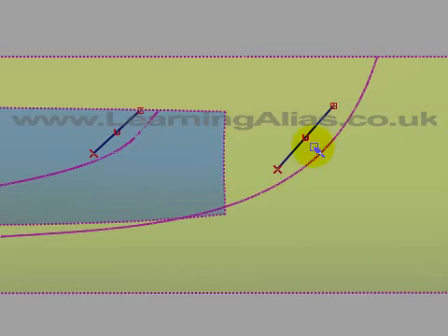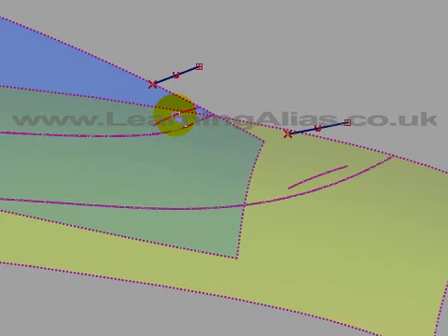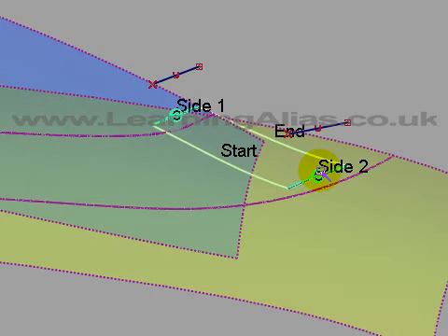Just put a curve where you imagine that the blend might want to end, and another curve where you imagine that the blend might want to start, and put them roughly at the angle you think the blend is going to be at, more or less, and then project these two curves, this one onto the shoulder and this one onto the C-pillar. Now just put a freeform blend spanning those two curves on surface with curvature, and it's a good idea to turn on your CV HUD so you can see what's going on.